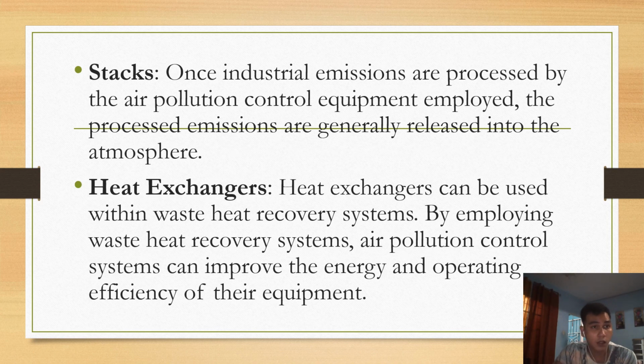The next one is stacks. Once industrial emissions are processed by the air pollution control equipment employed, the processed emissions are generally released into the atmosphere. Stacks provide an outlet through which the emissions are dispersed into the atmosphere, as well as prevent the emissions from re-entering the building. Additionally, stacks produce a natural draft which aids, when applicable, combustion processes. Next one is heat exchangers.